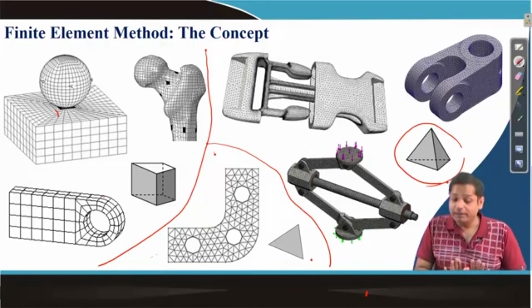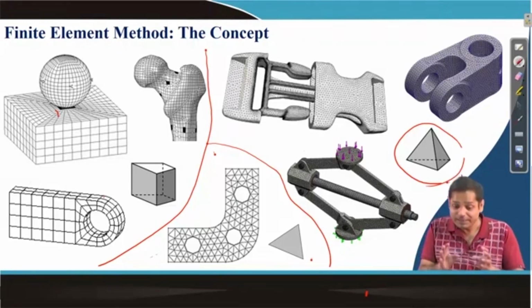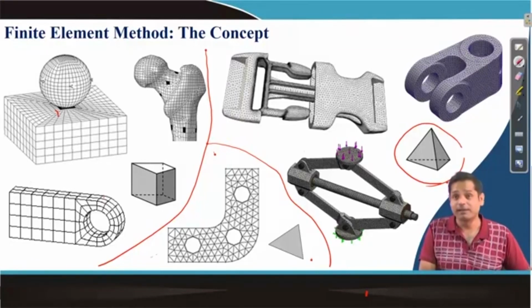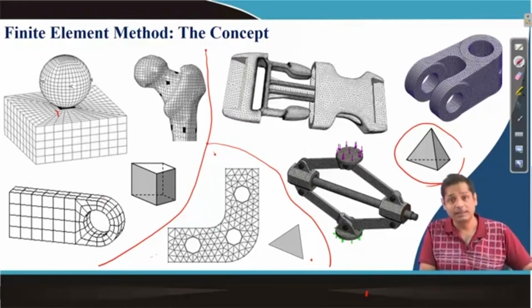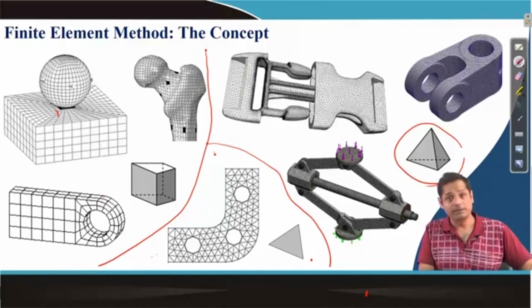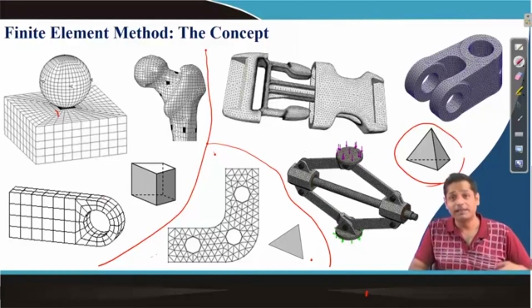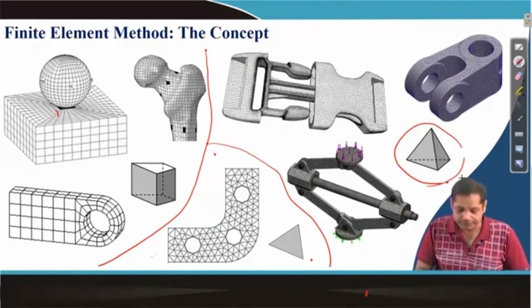If you have a background in the direct stiffness method, then please try to see the similarity. In the direct stiffness method also you did a similar thing. For building frames, you have written member stiffness matrices for different members and then assembled them to get the stiffness matrix of the entire frame. It is essentially the same, but in a more general way we do it.